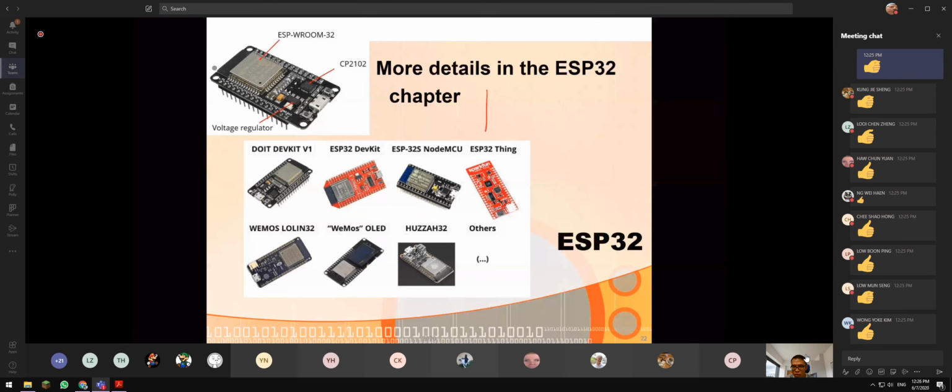For your information, a microcontroller has a UART, with transmit and receive. Your PC nowadays doesn't have a UART. Those old days, you had an old computer with a UART, which they named RS232. It's something like this, like I told you just now, a 9-pin connector.